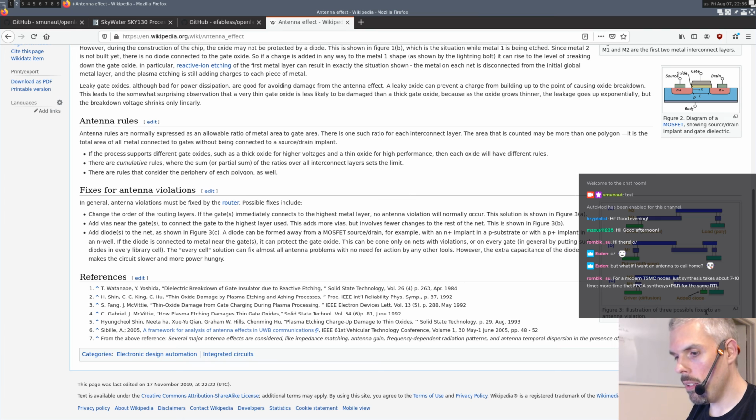And you still have a gap at that spot in the chip, so it did use space for nothing. But removing the antenna diode helps lower the capacitance of that wire, because the diode adds a small capacitance which slows things down, right?